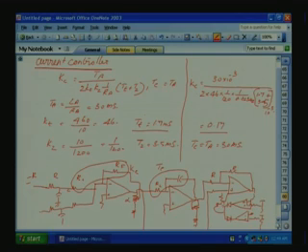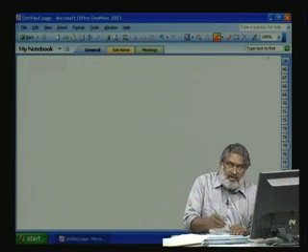This I have explained when we talked about the controller design. The same thing we can put it also here, so that capacitor should not go up plus 10 minus 10, and by independently controlling this alpha 1 and this alpha 2, we can fine tune the PI controller. Okay. The same way we can use it for the PI controller for the speed loop. Now let us talk about the speed controller.